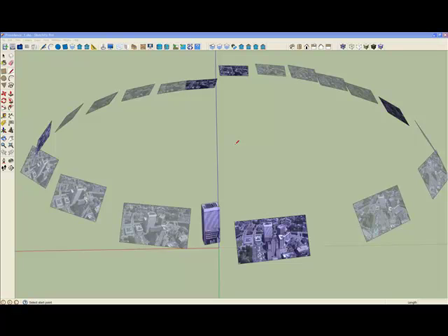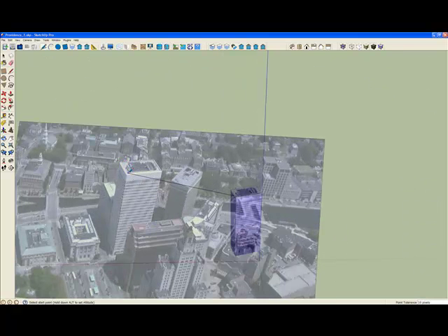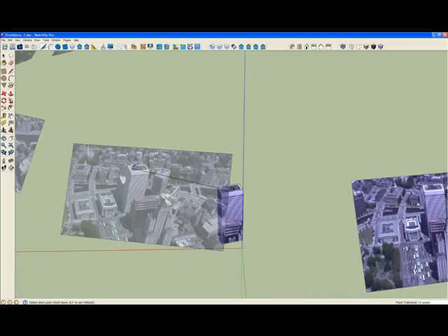This is concepts video 4 for the GeoSketch application, describing the inferencing in GeoSketch. The reason that GeoSketch inferencing is different than the standard inferencing in SketchUp is because we're usually constructing geometry by projecting from the 2D image space of an aux view to the 3D modeling space. So for example, these two edges in the image are not 90 degrees to each other, but when we project those edges into the modeling space, the corner will be 90 degrees, and we need to make sure that we obtain that 90-degree angle as we're constructing these models.